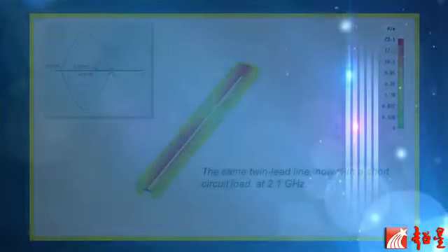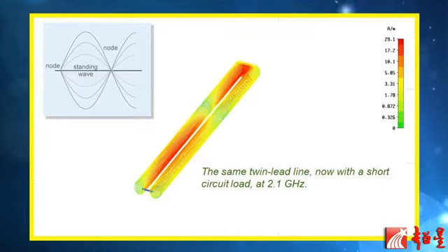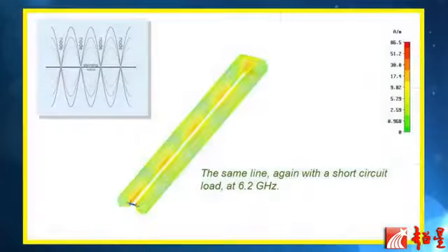Okay. Again, this is a short load where you have a maximum current here. And this line is much longer. You can see it's about 3/4 of the wavelength, almost a complete wavelength. Okay, so you can see that you have a lot of current here. There's almost no current there. There's current here. Okay, that's transmission, wave propagation.